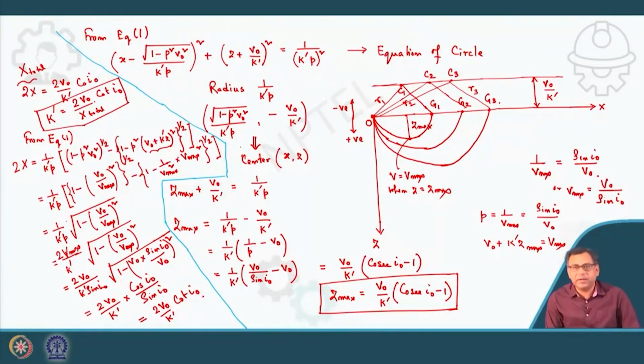So now this is probably the end of all the different cases that I have discussed. What are the cases I have discussed? I have discussed the seismic reflection test for horizontal layering, for inclined layering. I have discussed seismic refraction test for horizontal layering, inclined layering, and a layer where the velocity itself is changing with depth, or continuous change in velocity with depth. But in the previous cases, in a particular layer, the velocity is constant. But in the last case that I have discussed, there is a continuous change in velocity with depth.